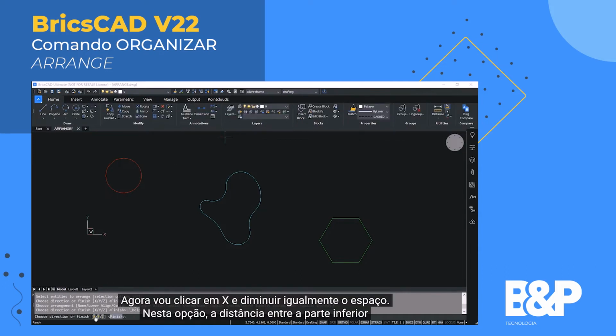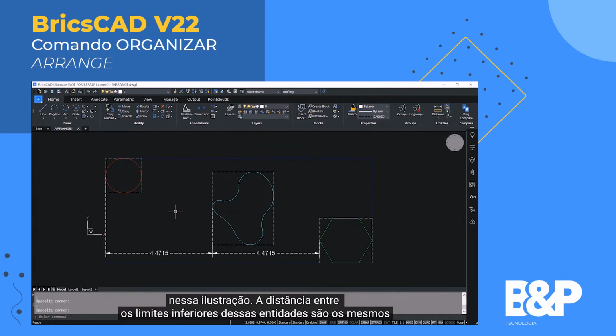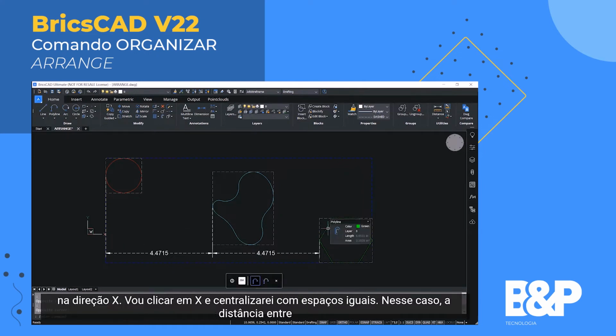Now I'll click on X and lower equally spaced. In this option, the distance between the lower bounds of the consecutive entities will be the same along the x-axis. And that is clear from this illustration. The distance between the lower bounds of these entities are the same in the x direction.